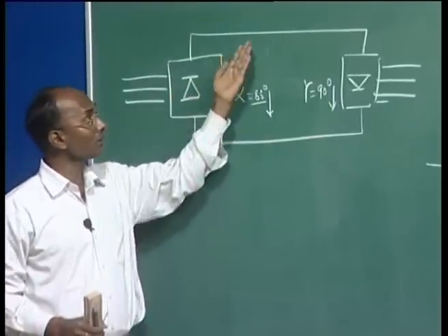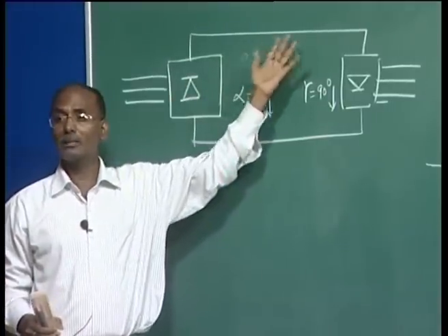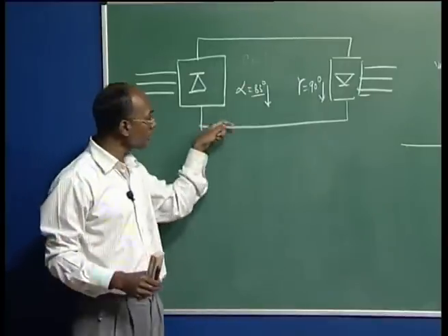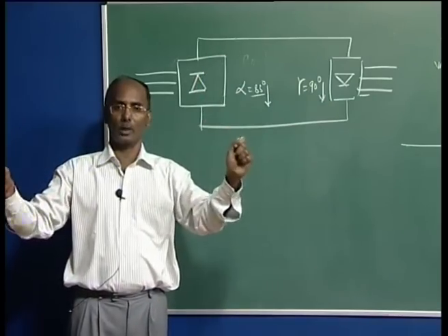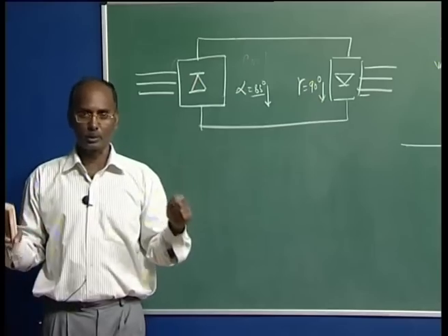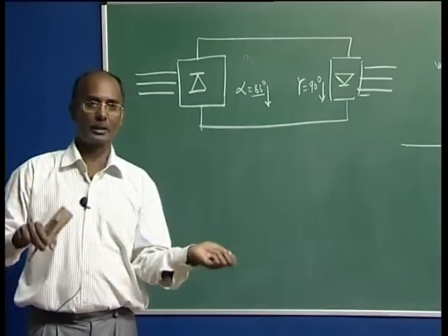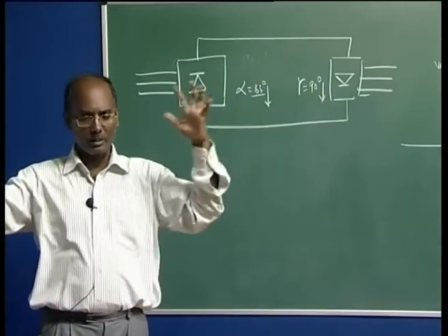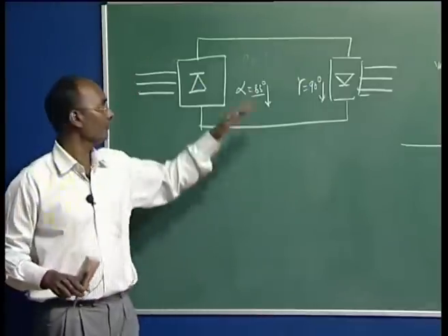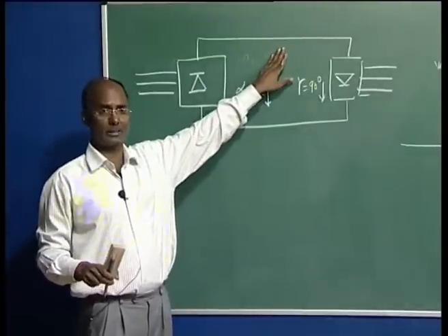because once the current is flowing, if there is some problem of insulation or anything, there will be a huge short circuit. So, we try to increase the voltage and see whether the line is okay or not, even though a small amount of current is flowing. Once it is sustaining that voltage, if there is some flashover here and there in the towers and insulators, then you can check it and stop it again very easily, because the current was very low.